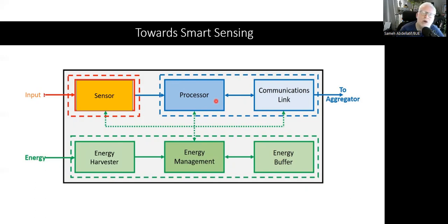Additionally, as we will discover through our course, most of these sensors produce a very low voltage, which needs some sort of amplification stages to be processed. A good example here, again, is the mic. Whenever you sense the voltage produced from a microphone, you will find that this voltage is very low, a millivolt, sometimes even at the microvolt scale. So again, this is another sort of processing. And as we will have an array, or based on our course, a network of these sensors, you will need a communication link, or what we can call a transceiver. It can be an RF transceiver, an optical transceiver, or different forms of wireless communication techniques. So this is another added block in our smart sensing units.